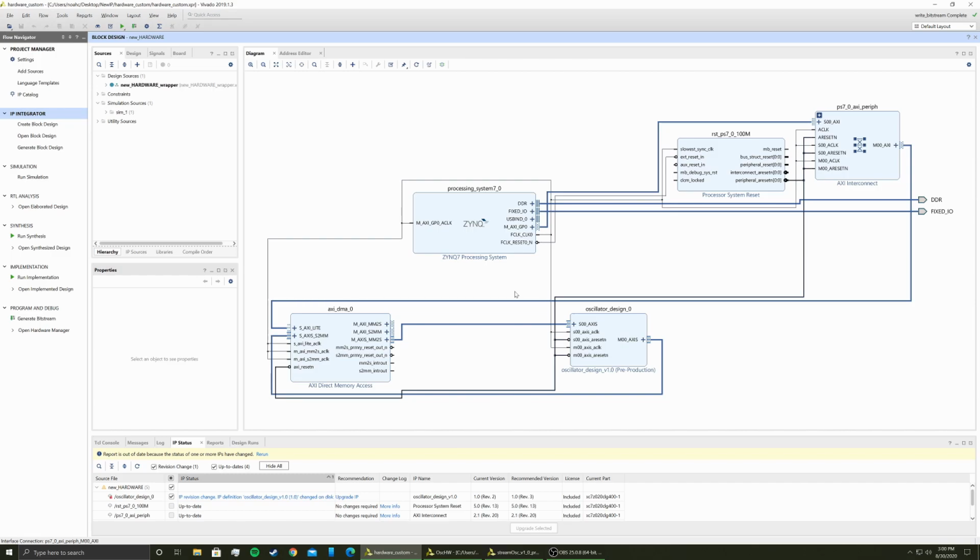That's essentially how you create your own IP design based off of Verilog and VHDL, primarily Verilog. That teaches you how to use that and also how to set it up with the DMA so you can extract data and record it from there. Again, you can look up how to use the DMA using the appropriate documentation, whether it be from the PYNQ website or whatever system you're running on.